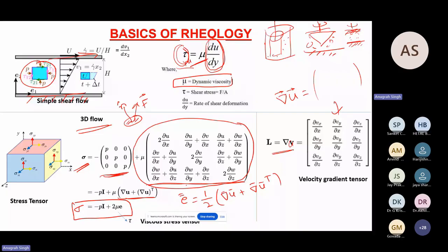So in 3D, you will have to relate stresses to the velocity gradient tensor. And when you do computation in 3D, it becomes even more challenging, because you will have to relate not only various components, you'll have various kinds of interaction between multiple particles. But this is all about it: once you can compute this relation, you can compute the rheology.